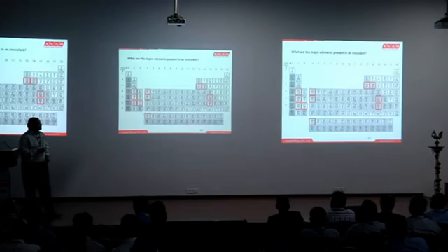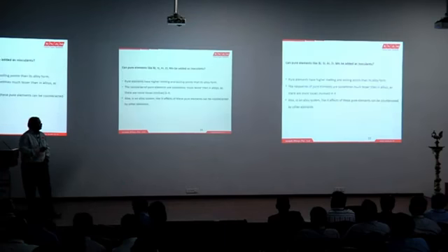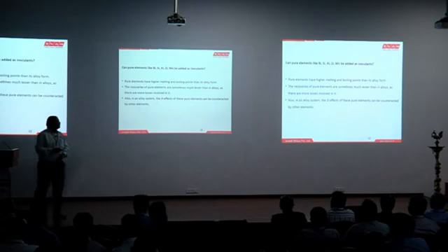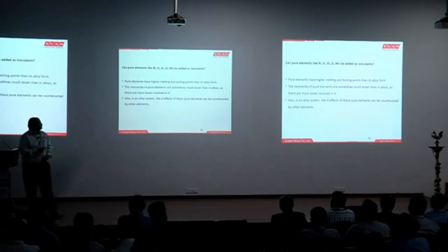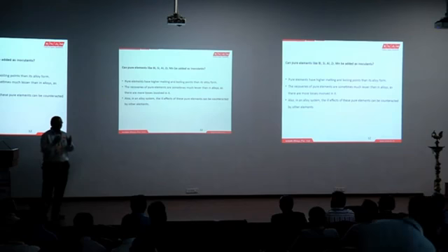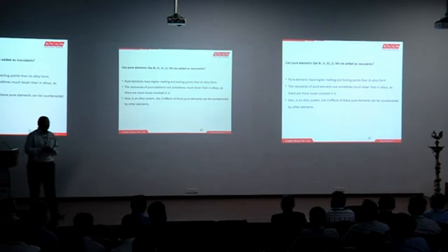If these elements have been identified, can these elements not be added in pure form? Can I add pure bismuth, pure silicon, pure aluminum, pure zirconium as inoculants? Pure elements sometimes have a higher melting point. The reason we go for an alloying system is that we maximize the properties which a single element can give, and we supplement the negative effects with the other elements present in the alloying system. Say, for example, iron.